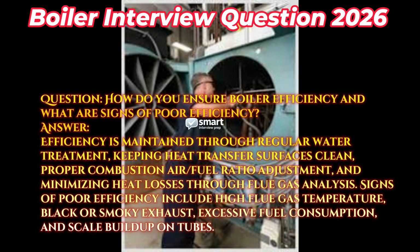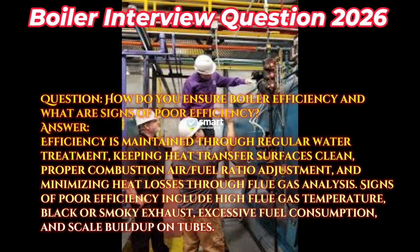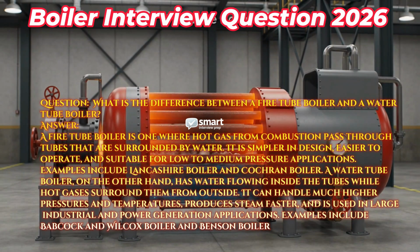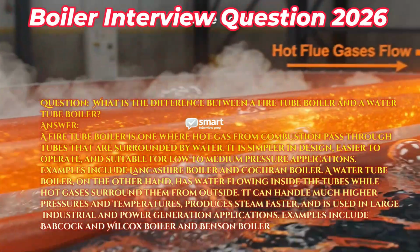Answer: efficiency is maintained through regular water treatment, keeping heat transfer surfaces clean, proper combustion air/fuel ratio adjustment, and minimizing heat losses through flue gas analysis. Signs of poor efficiency include high flue gas temperature, black or smoky exhaust, excessive fuel consumption, and scale buildup on tubes.